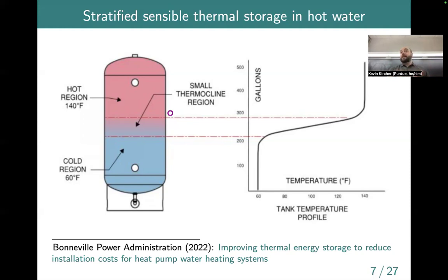Also, we have lower electricity prices here overnight. So the idea would be during summer cooling season that you would make a whole bunch of cold water during the night. And then during the afternoon, when demand for electricity peaks and also electricity prices are high, you would use that cold water instead of running the chillers to provide air conditioning to campus.